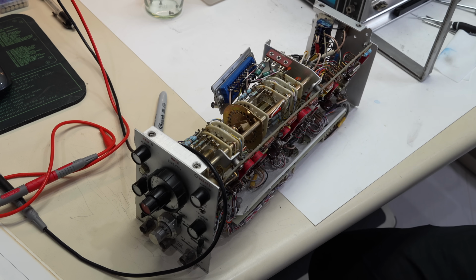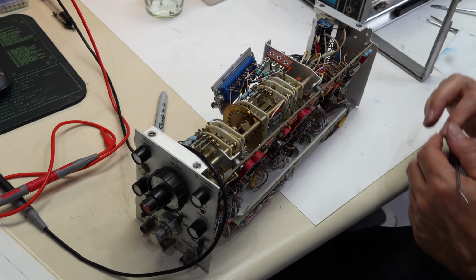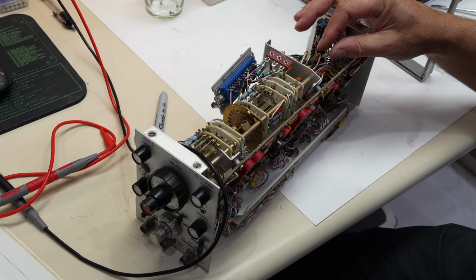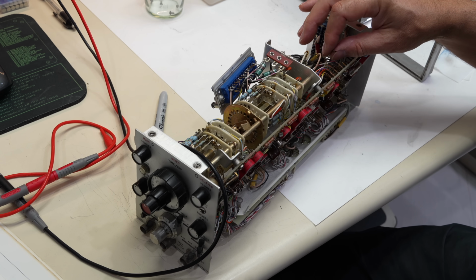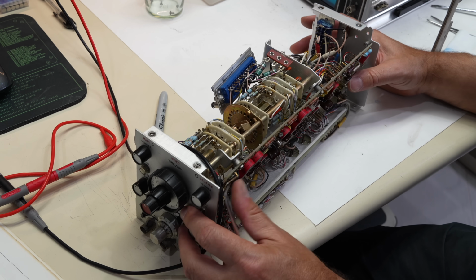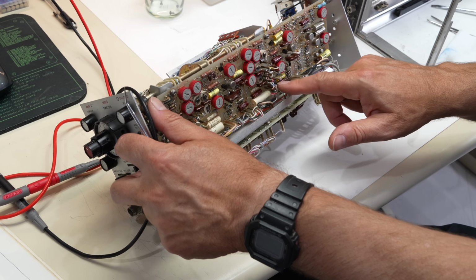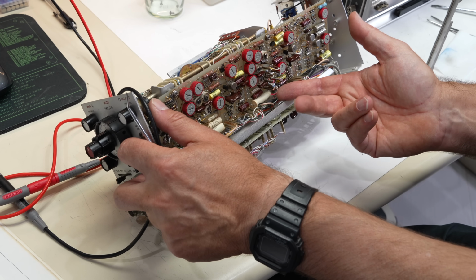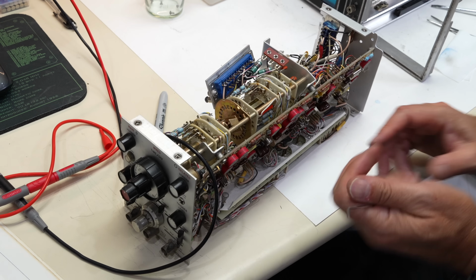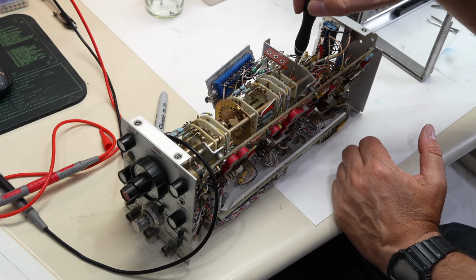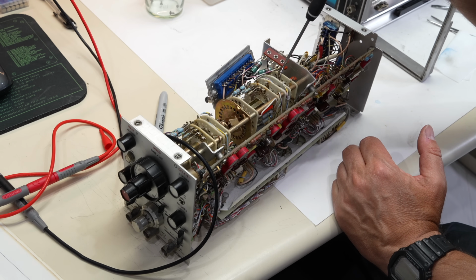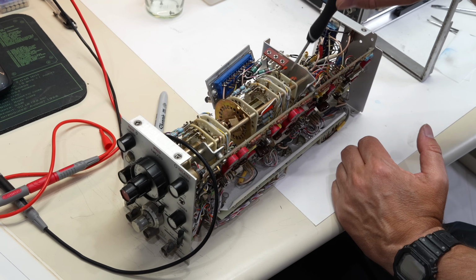One hour later. Alright, after an hour of searching, I think I might just have found it. And I had to take it fully apart. So that's the wire that should not be attached to minus 12.6 volts and is. Then it goes at the back, I lost it for a while, but then I found it. It goes back through the board right here, and it goes all the way to that rotary switch here. It's on the common back there.